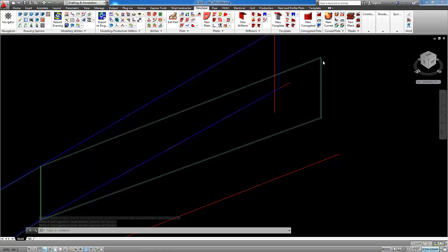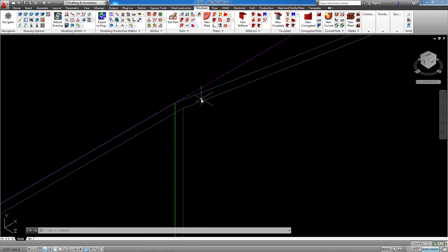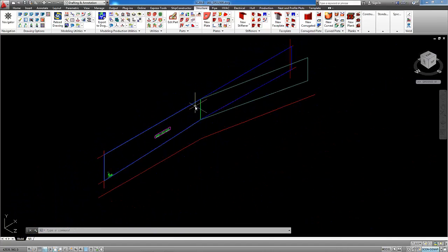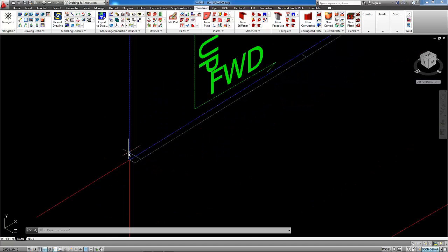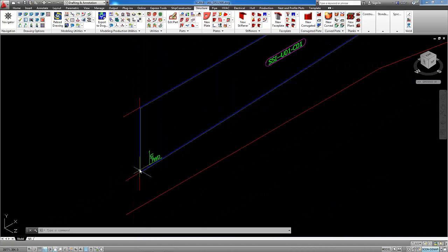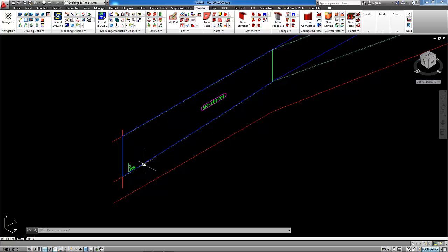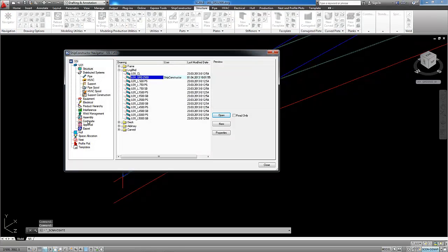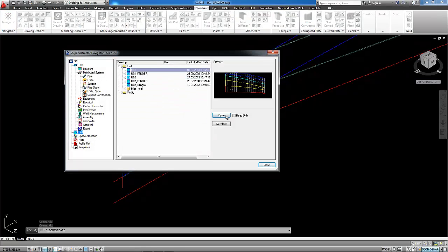Now you can see that plate with knuckle was created, and thickness goes inboard, complete thickness goes inboard, which doesn't create any collisions. We can check this also if we will open hull drawing.